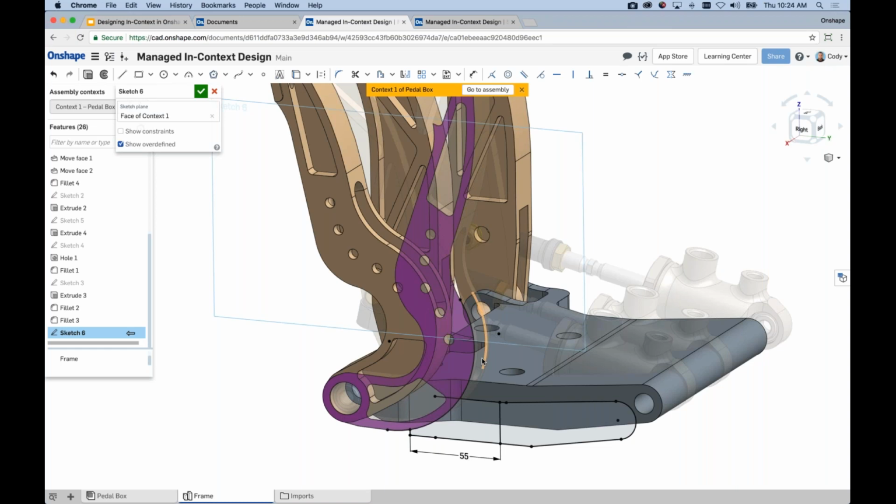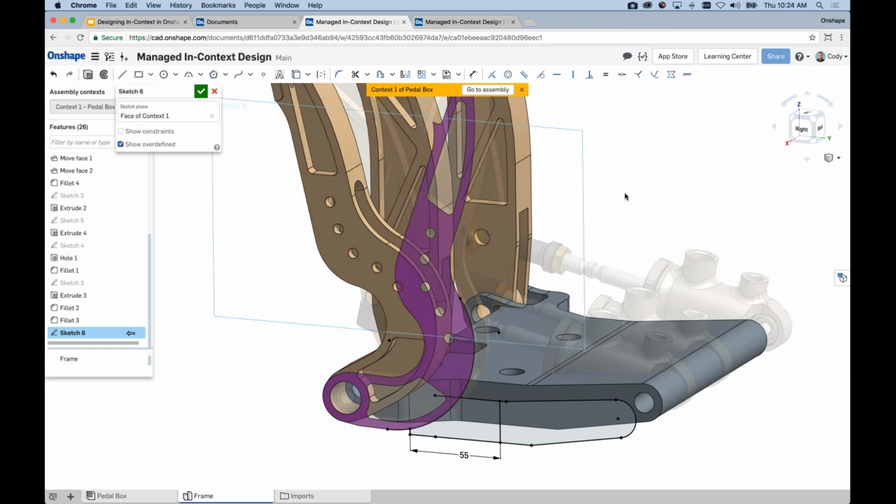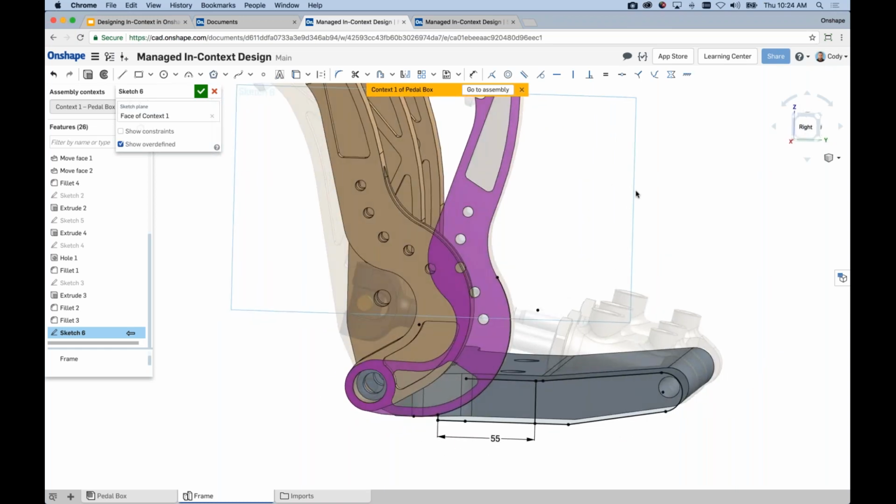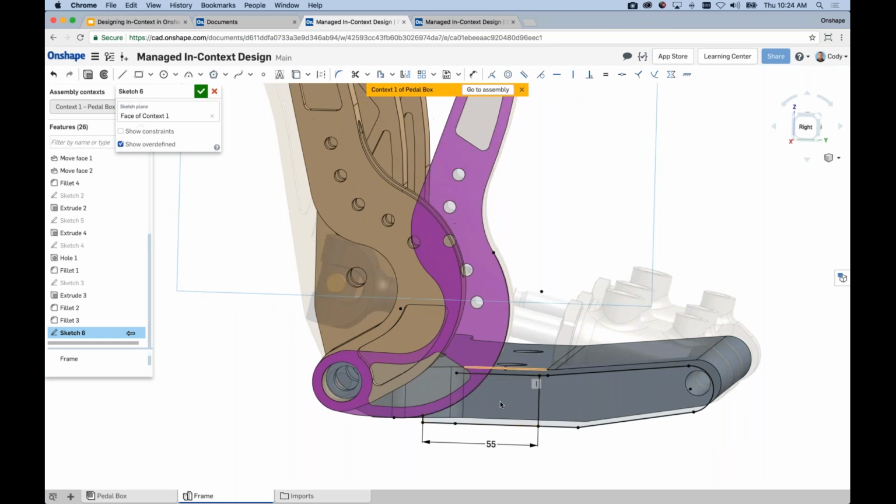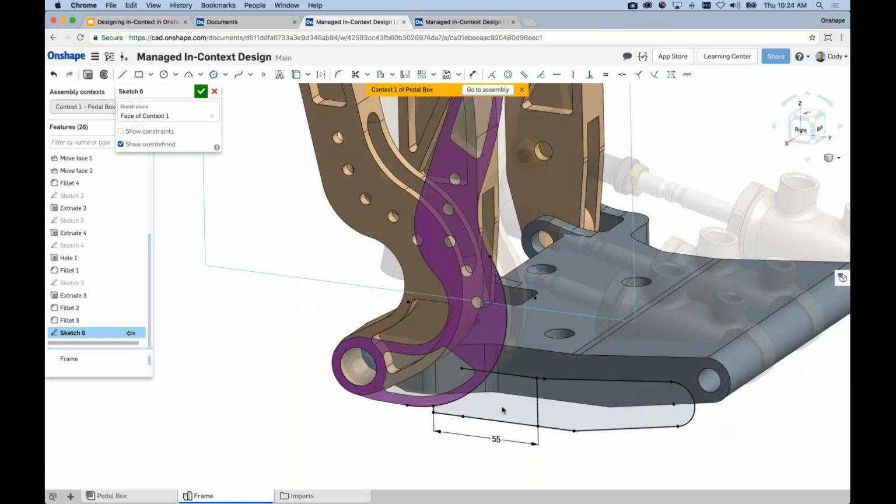And so that's important because, remember, at that moment when you click that, it captures those positions, right? Anything that's hidden or shown with the position of all those things, then that's what it brings in. So I moved that pedal back to that position where I want it to stop, and now I'm designing around that position in the Part Studio, right? In the Part Studio context, right?